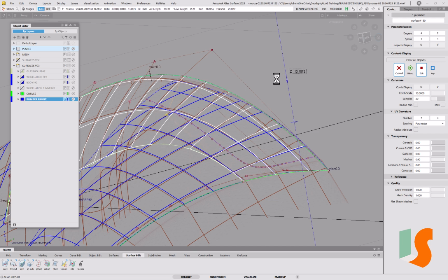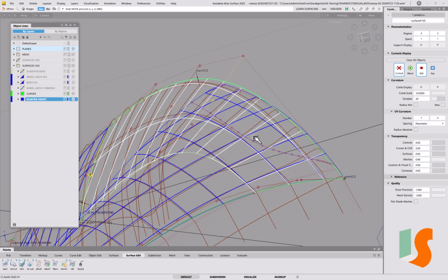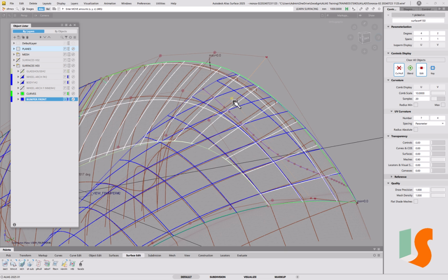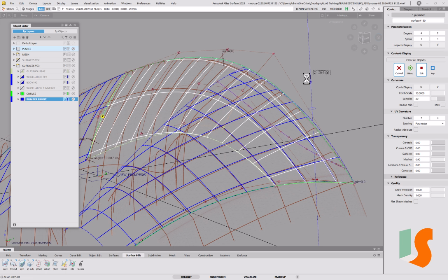So you can see as I pull this point back here, so I'm pulling that in the Z direction of that plane, but the intersect now starts to go where we want it to go. But what we will have to do is we'll get this wobbly looking intersect, and then at some point we're going to design a curve going across there, because I think that is important that we control that. It may not be necessary, depends on what the result is, but usually you get the rough intersect in place, and then you have to design it and control it absolutely.